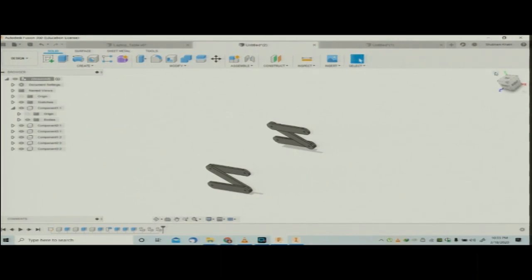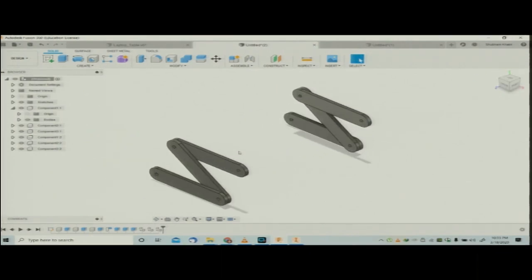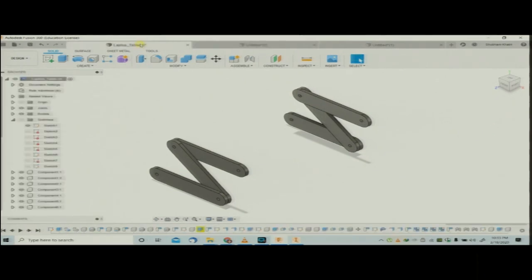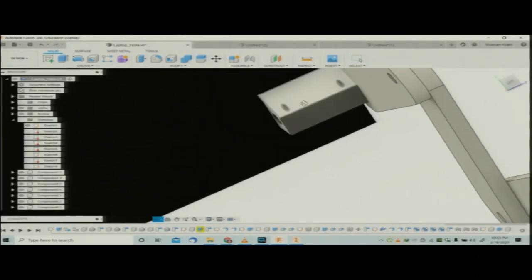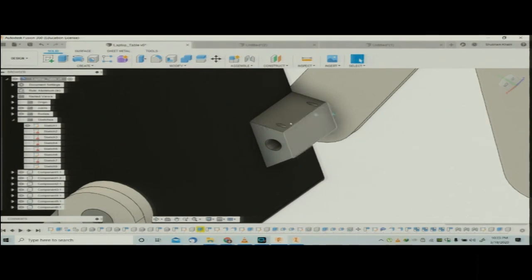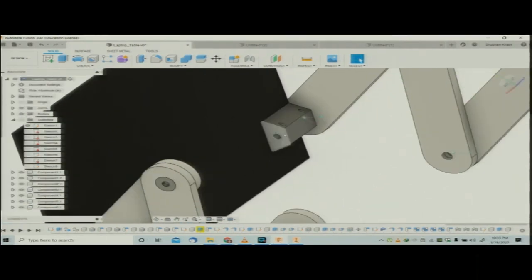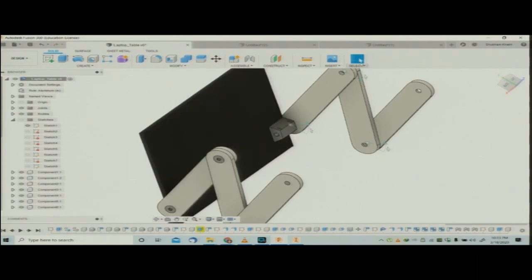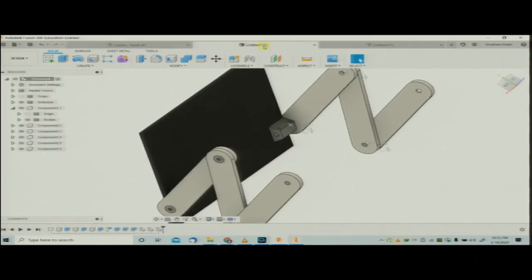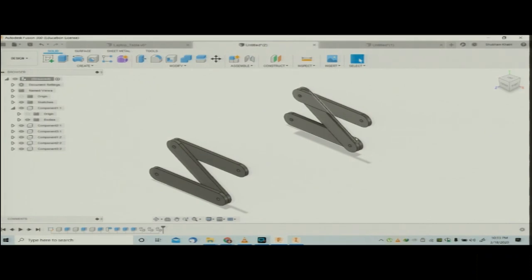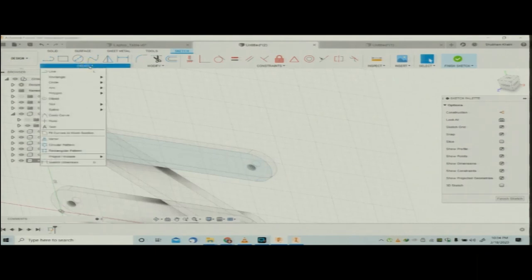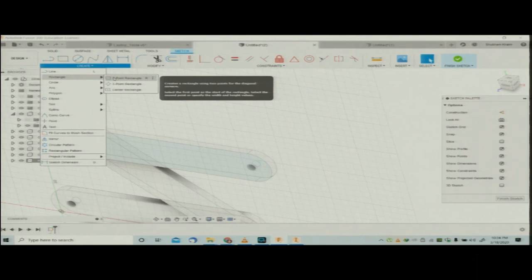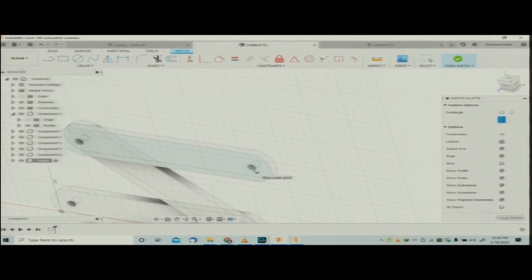Next thing that I will design here is my sheet metal component. The top face has to be designed. Before that, I have to design a hinge here. This hinge will be fixed below the sheet metal component. This hinge support for sheet metal is to be created. I will just make a simple rectangular hinge here. So, first we need to make a sketch. For that, I will pick a 2-point rectangle or a center rectangle, because we have the center here. We select the center here and make a rectangle.